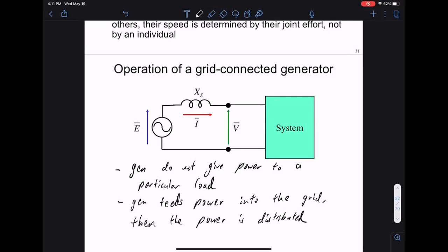So you said the US grid is broken into 3 sections. If we all are running 120 volts at 60 hertz and variations by that little bit are bad, then how are they all running separately and why aren't they all just running the same thing? Sorry, so we're all running 60 hertz, right? But we may be running at, let's say, 59.5. The Eastern interconnection may be running at 60.5. You do not want to connect these two grids together at this point. 1 hertz is big enough of a change. Within our Western interconnect, our frequency is fairly balanced. So your frequency is probably very similar to a frequency that's in San Diego. In each system, frequency is quite similar.